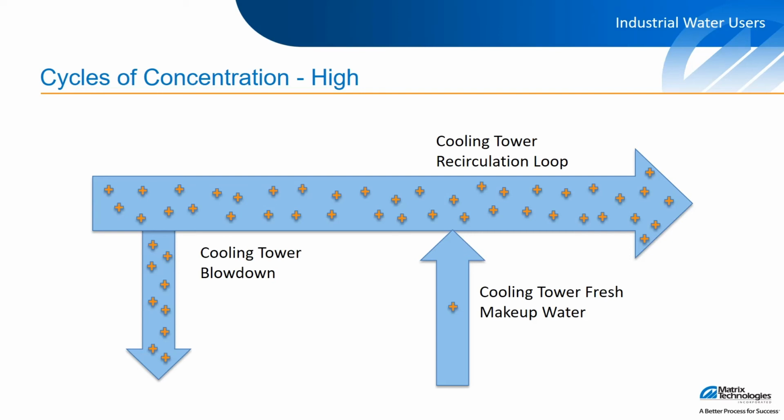Other effluent flow streams from industrial facilities can also be treated on-site for reuse within the plant. Depending on the composition of the effluent streams, filtration and treatment options can be selected as additional treatment after the site wastewater treatment plant to meet quality requirements for reuse within the process or as makeup cooling tower water.